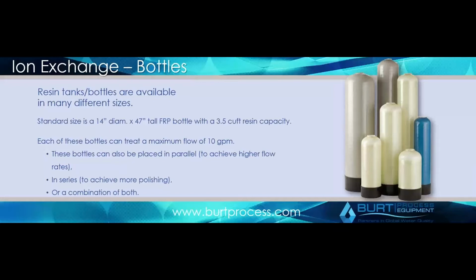It's interesting to note, ion exchange bottles, or where resin is put in the system, can be in a lot of different places. Very often it's in the polishing loop downstream of your system, but very often it's also right after your RO. It's not uncommon to go right from your RO into an ion exchange bed, even though you won't be polishing it through your loop. It's very common when you don't need quite as high a water quality.